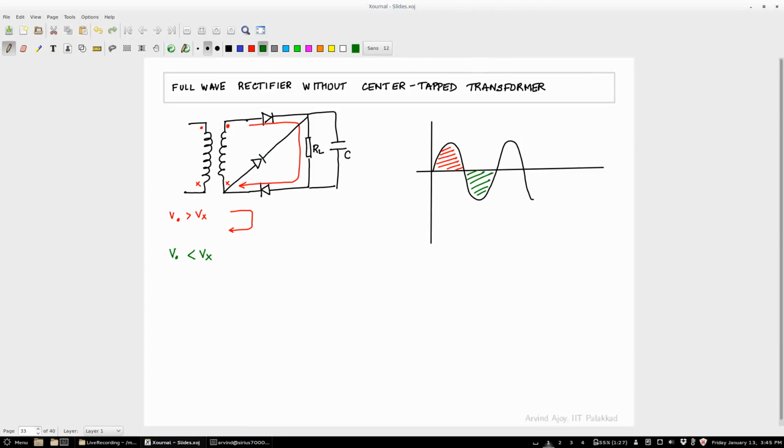So one way of doing that is, let me just draw these two diodes and then you can see what's happening. Okay. So let me draw that in black, and then I'll draw the current direction in green. So assume I have another pair of diodes connected. So I connect this to this. Okay. So the current will go, because this is more positive than this, current will flow this way, and then through the load it will again flow down, and then now you have to take it back. So how to take it back?